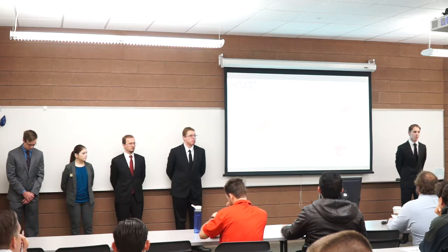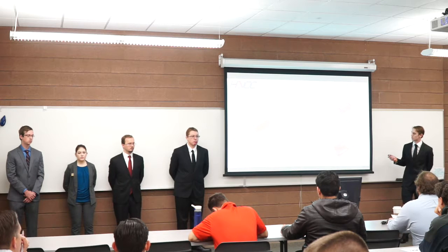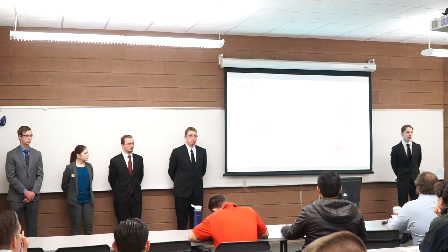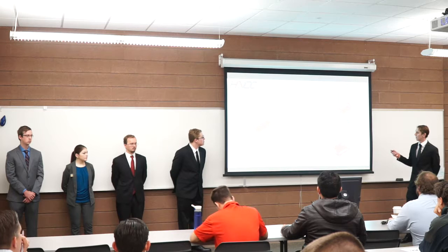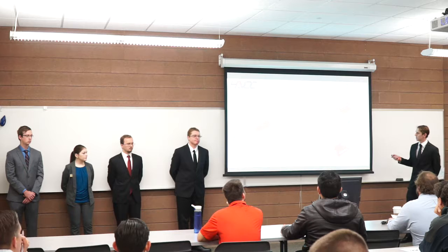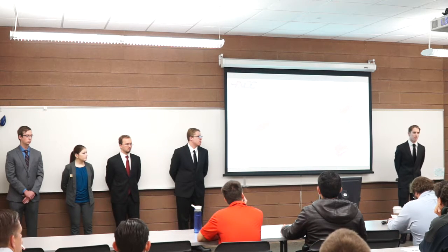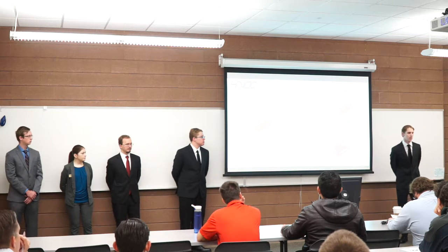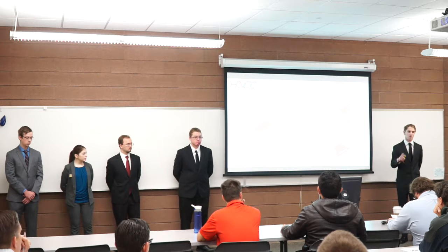Here is a picture of the proximal phalanx on the standard finger. It consists of 2 main components. There's the phalanx itself, and then there's the phalanx cover, which covers up the tendons. As you can see, we have multiple passageways for the tendons to pass through. We can send them in through the bottom here and send them through the entire finger, through the entire phalanx up to the next one if we want to. That way we can actuate multiple joints within the finger.